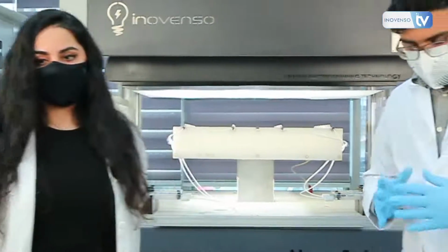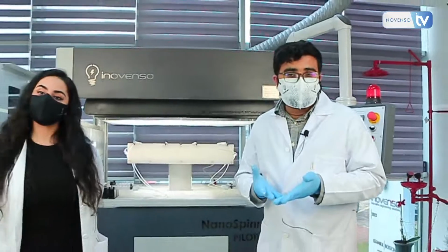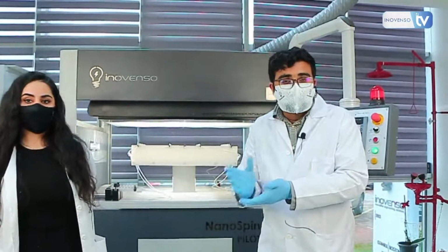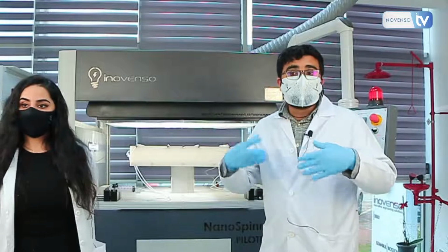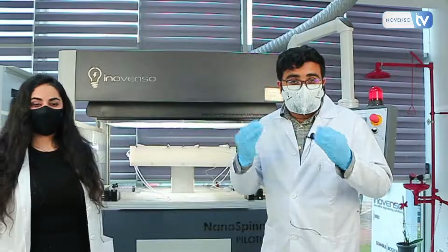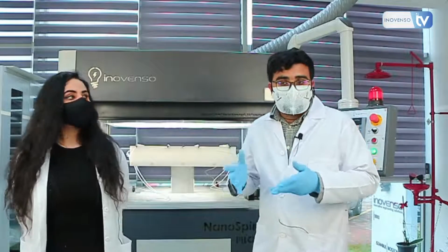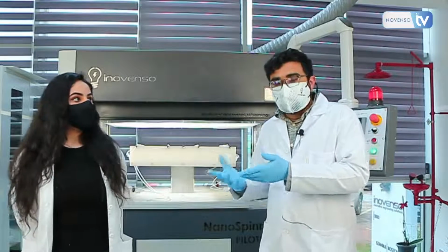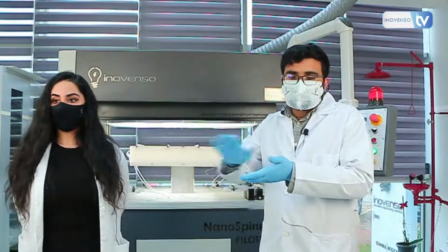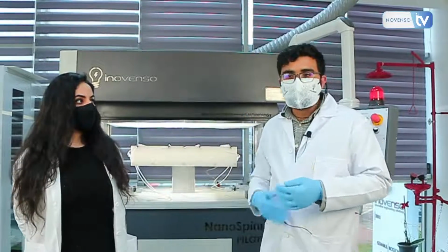So another question, as we have answered previously: how is the cleaning process of the needles? As I said before, the needles need to be cleaned with the solvent they're used with. For example, if you're electrospinning a particular polymer with, say, DMF or acetone, it would serve you well to dip or bathe those needles or rods in that solution for a decent amount of time. Then you can wash it off and dry it with air. For a generic answer, you could just use acetone in most cases and spray onto it, then use water to rinse, and of course dry it with air.